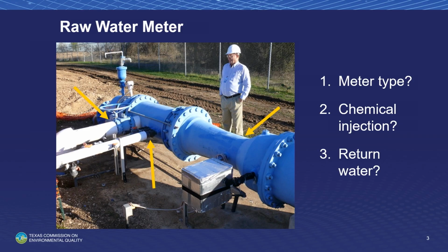Other issues that sometimes you get hung up on, and this is really a pet peeve of mine, because regulations require you to have those meters tested once a year. And quite often, what I've found is the people that do that testing will come out and slap some kind of an electronic meter on there and measure the 4 to 20 milliamp signal and call that a calibration.